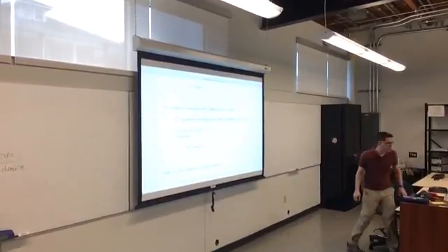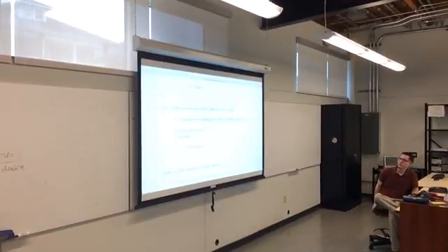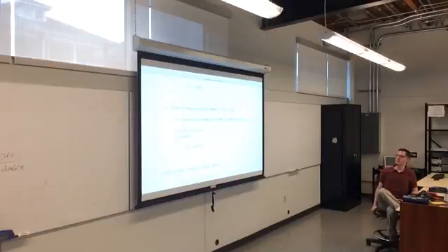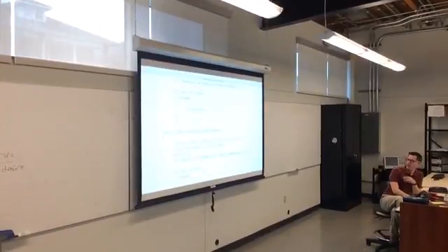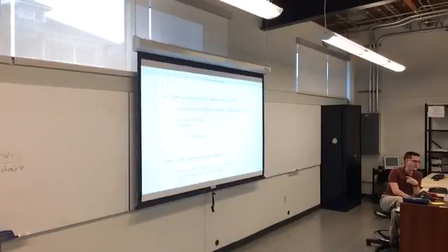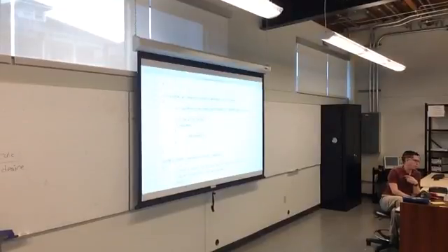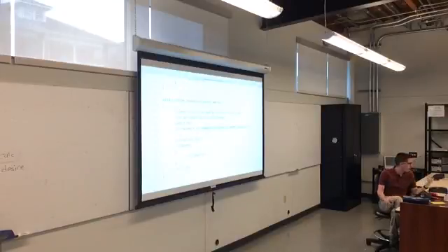Same thing with the read register. The write register works exactly as you think. It takes an address, and it takes a value, and it writes it. It returns true or false, whether or not it's successful. The read register is a little different. Normally with a read function, you return the data that is read. I wanted to return both the data that was read and a true or false about whether it was successful. So you've got two options there in C++.